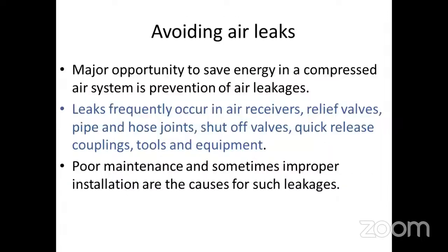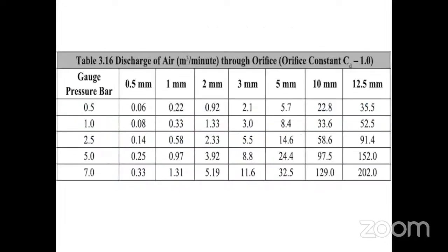Mechanical stirrers and all. Avoiding air leak. Sir, the major opportunity to save energy in the compressed air system is prevention of leakage. Leakage frequently occurs in air receivers, relief valves, and all. Poor maintenance leads to such leakages.